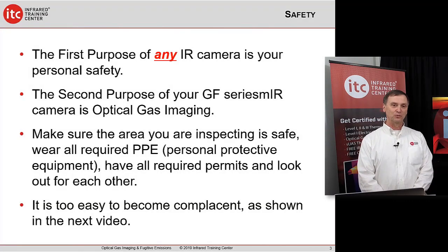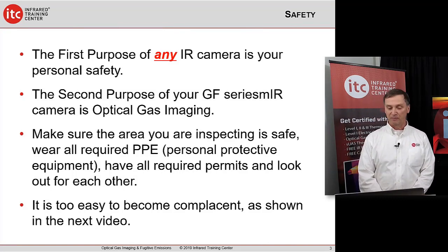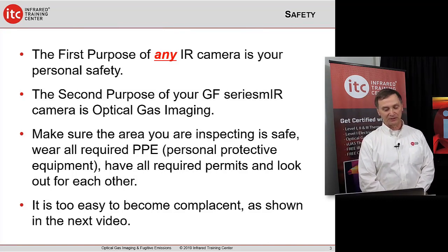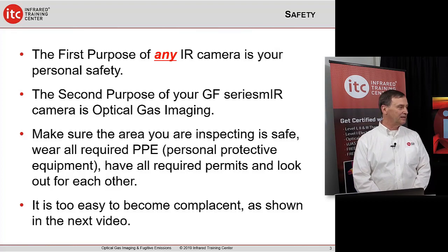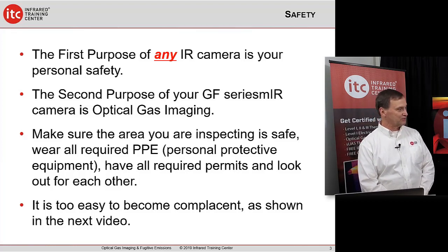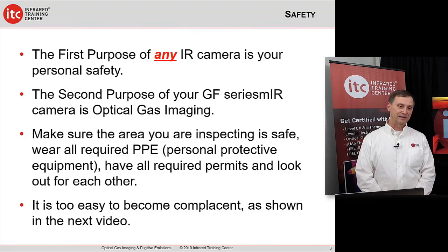Regardless of what camera you have, whether it's an optical gas imaging camera or a regular thermography camera, you should always make sure that the first purpose of your survey is your own personal safety. And we've seen this many times where folks have walked into a gas stream, or walked underneath something that was very, very hot, like an electrical connection. So prior to even entering an area that might be classified, where you might need a hot work permit, you should do a wide area scan.